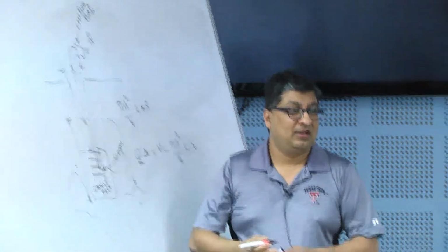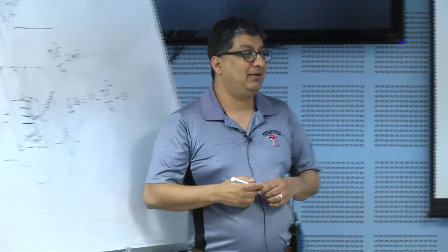Okay. And by low flow, it's usually less than 100 mL an hour. So you're pumping about 1 to 2 mL a minute. Very, very low flow. And what you do is, when the water comes out, you take pH, specific conductance, EC, redox, those kinds of measurements. And once that stabilizes, that's when you collect the sample.